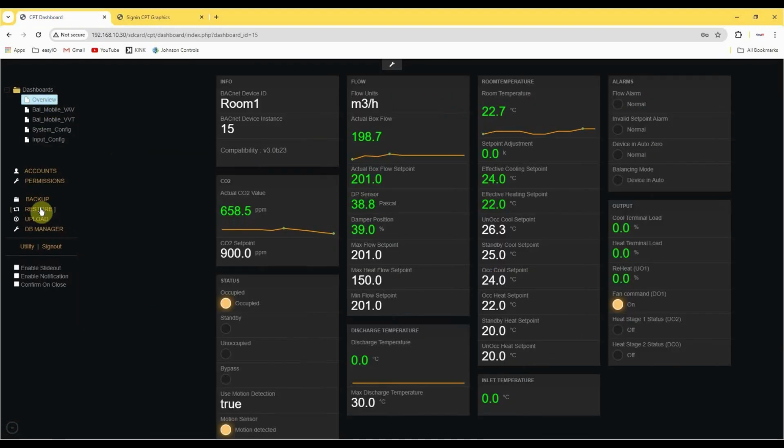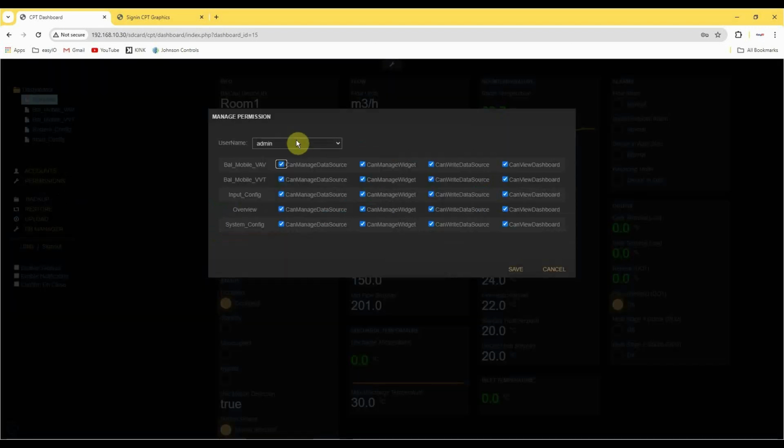Would also like to briefly show the Kiosk Mode, which is available in this FW-VAV but also in any other FW controller from version 23 onwards. But it is also available in the FS controller from version 61 onwards. On the permissions page, select the kiosk user. Here you can specify permissions for this user per page. So page view, or page view but also control.